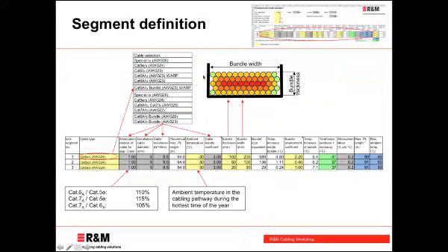However, this number of cables is not important for the calculation, because according to the standard model, a bundle is something which has a compact round shape. So what we need is an equivalent round bundle that has the same thermal properties as the bundle we have in this trunking system.